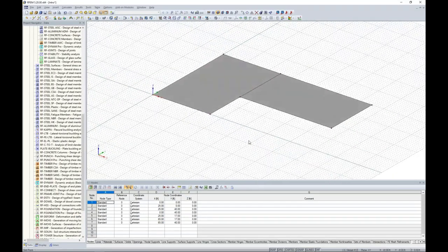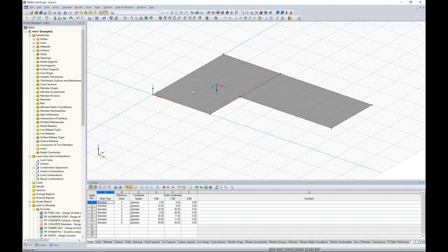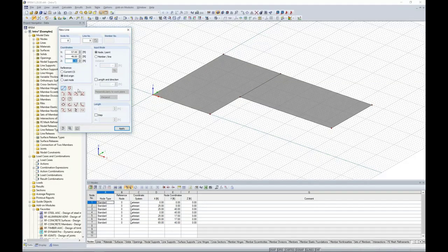So the surface over on the left, I'd actually like to extend it out in a semicircle in the front. So how I can do this is just by drawing a new line element. Now a line element makes up the boundaries of these surfaces. So I can go up here to my tool to choose a new line. Now, again, similar to AutoCAD, of course, we have just straight lines, but you'll see here many other options such as arcs, polylines, splines, circles, so relatively few limitations when it comes to complex geometries.